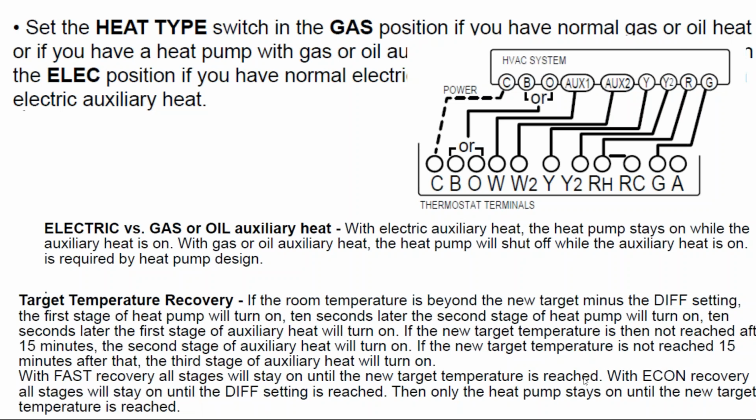Well, what we see in this particular thermostat model is that they have additional auxiliary relays that could be used to provide a little bit of energy management with just the existing resources that you already have on the home. So a good one for an off-grid system would be to trigger via an auxiliary relay an electric heater, like an electric space heater.